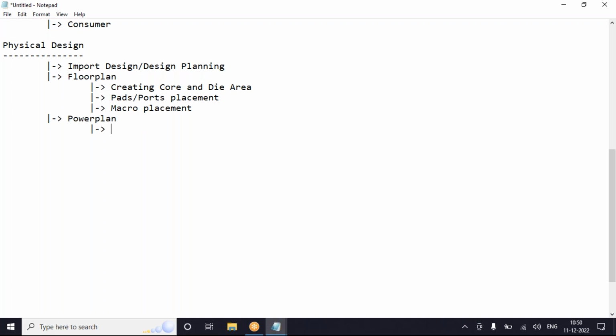So once I place them, because of cell usage also, the power might get dropped, right? Then I cannot be able to find it. Let's keep it like two cases, static and dynamic. Static case I'm checking, and dynamic case also I need to check. Before placing those standard cells, we are checking the static related. Whether that particular power passage is good or is there any problem, I need to get it verified and fixed.